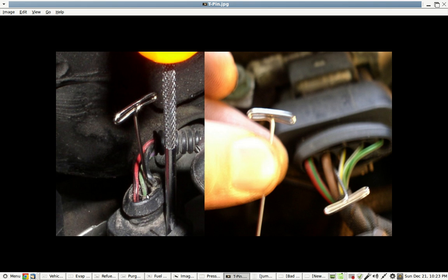And on most of the Toyotas, you need to look at a wiring diagram, but most of the Toyotas use ground, so they have power running to them at all times, and the computer just grounds it. A word of caution: if you're doing it this way, you better be sure what you're doing, because you can fry the computer. The other side of this wire is connected to the computer, and it's a very expensive mistake if you let the smoke out of it.